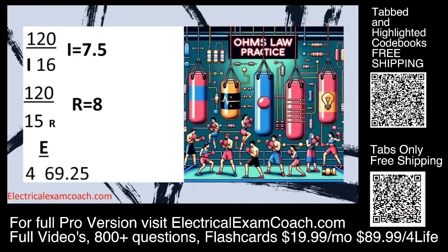We have this scenario, and we're solving for voltage. We have 4 amps and 69.25 ohms of resistance. We take and multiply that out, multiply 4 multiplied by 69.25, and that lets us know that we have 277 volts on this circuit. Great job.